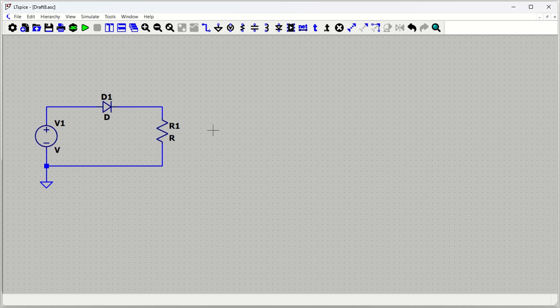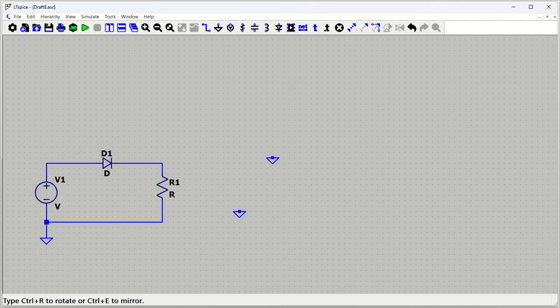Coming back to the point where we are going to draw this particular circuit quickly. If you want to put down a resistor or a capacitor or things like that, there are toolbars given here. This is the ground. If you press this, you will get a ground. Keep pressing and you will end up with as many grounds as you want to put. Whenever you are in this mode, keep left clicking, and it will keep placing a ground on the circuit. If you right click, it will go away, or you press Escape, it will go away. This is how you come out of this mode.